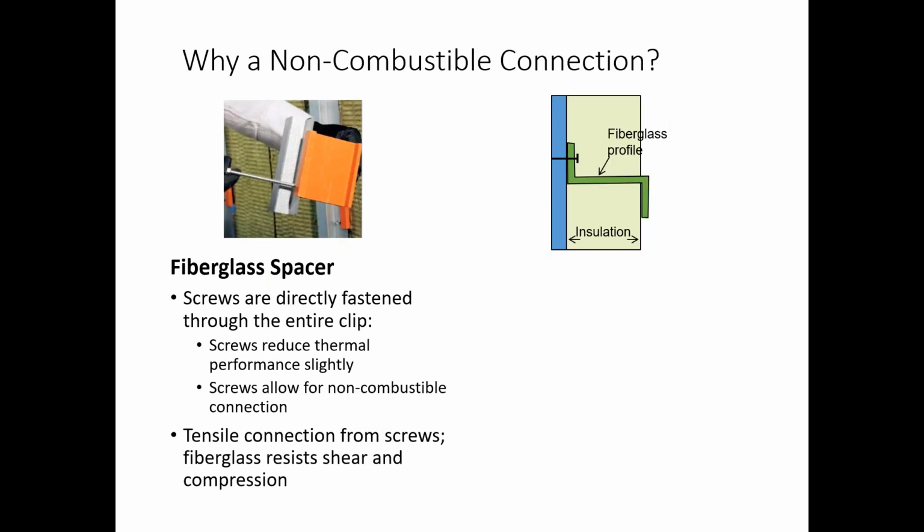In comparison with that, a composite component can really be as dense as it needs to be. Some of them, like the thermal spacer there on the left, are strong and do not frequently need tight spacings. But if you came to a part of a building that is just going to trigger tight spacings because of windows and corners and things like that, you could take a composite cladding support and make it more densely spaced without a significant thermal compromise, because there's such little heat flowing through these composite components to begin with.